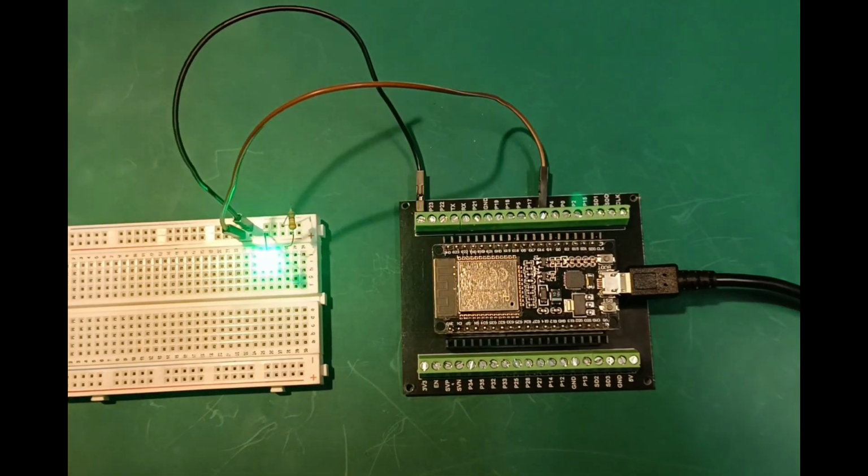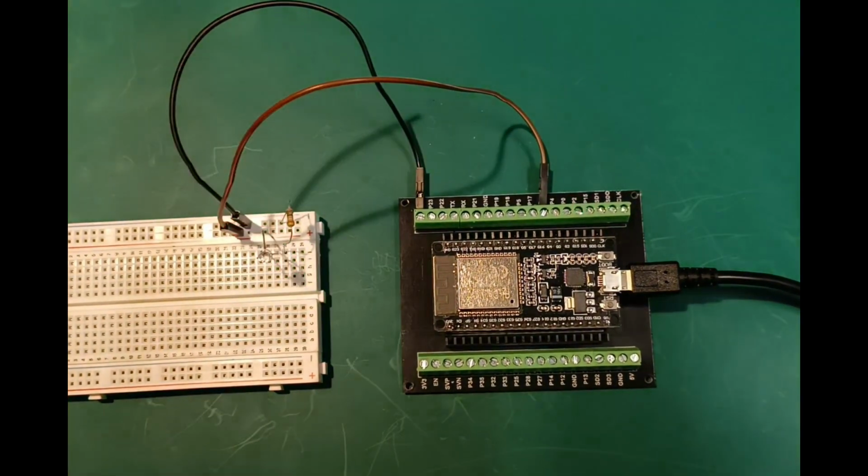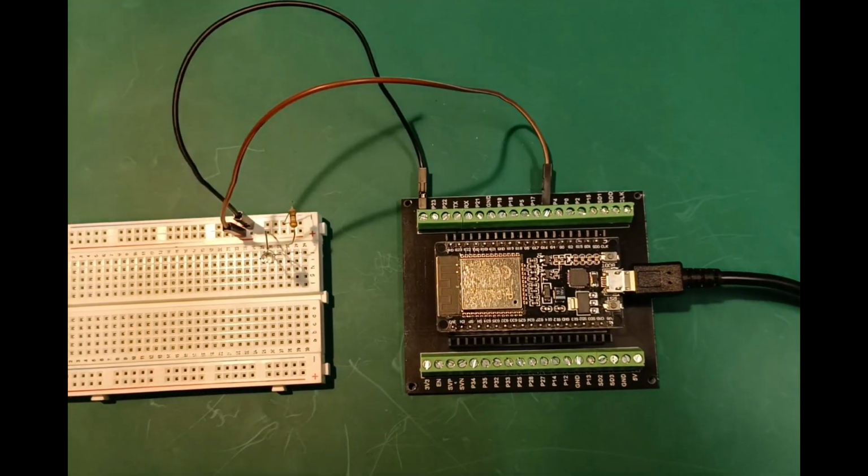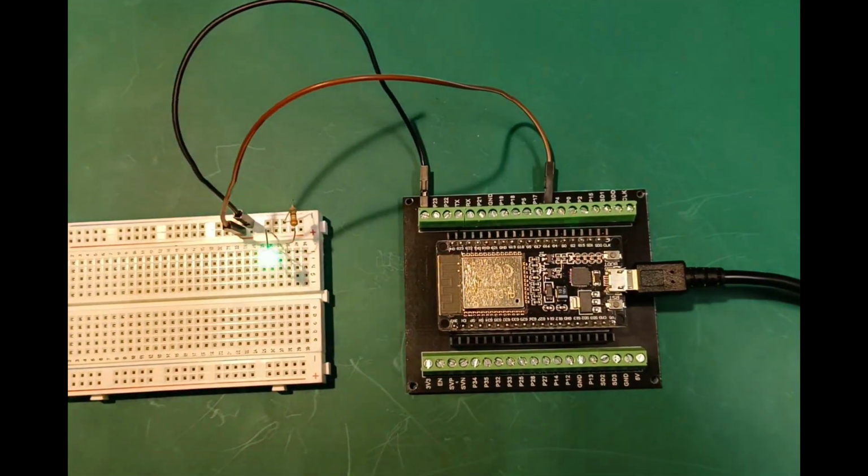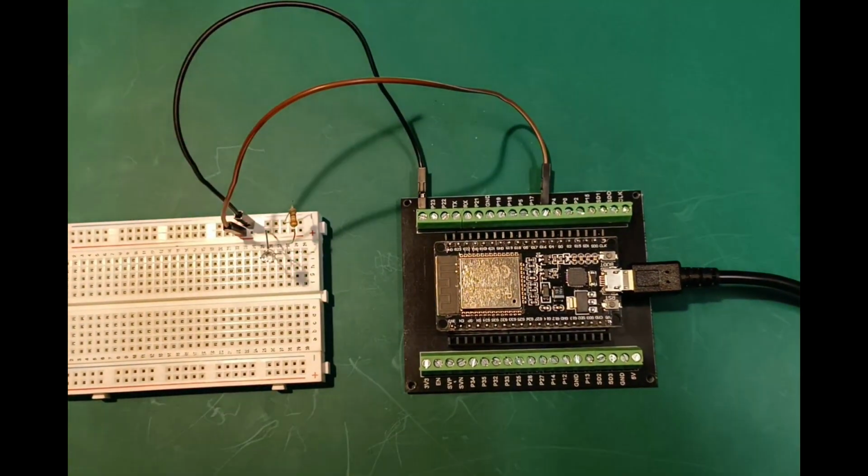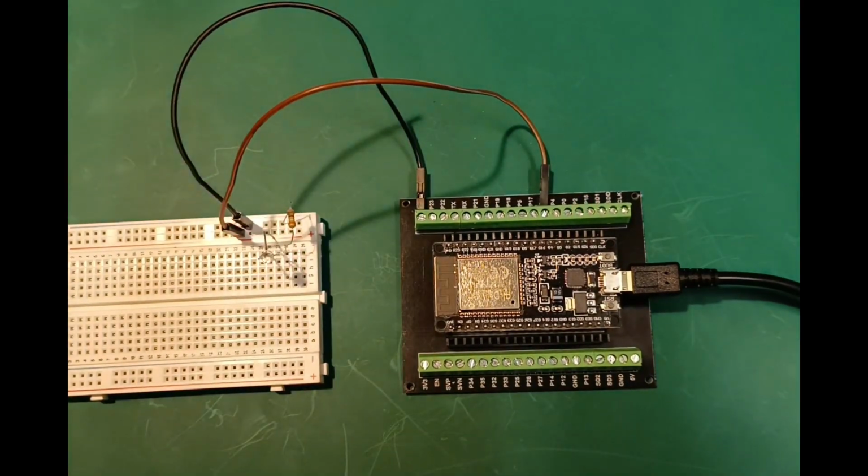As shown here, using GPIO pin 16, connected through a 390 ohm resistor in series with an LED to ground, the LED blinks brightly at half-second intervals, confirming the installation of the mockup.